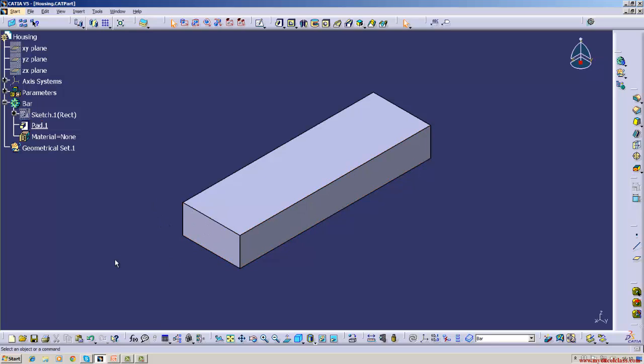That means it is a different part, but it is in the same Catia part. Totally it is a fabricated system. It is not an assembly, it is a complete system. A plate is welded to the bar. It is one single part, made out of a plate and a bar. But it is not an assembly, it is a welded item.